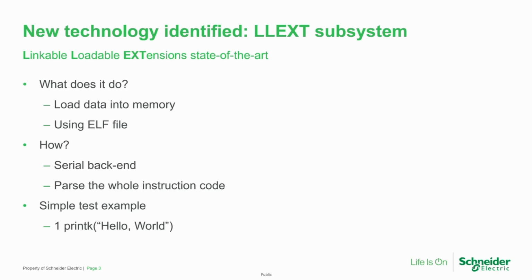Basically, what it does is that it takes some piece of code. So basically, it uses an ELF file. ELF is a really well-known format, I think it's executable and linkable format. So basically, when you build a firmware, you end up with an ELF file that you want to put on your device. LLEXT is using the same format, but this time instead of reflashing your whole product, you just add the ELF file on top of your product, you load it, and you execute it on top of it. So you don't reflash anything, and you don't reboot anything, just load it and run it.